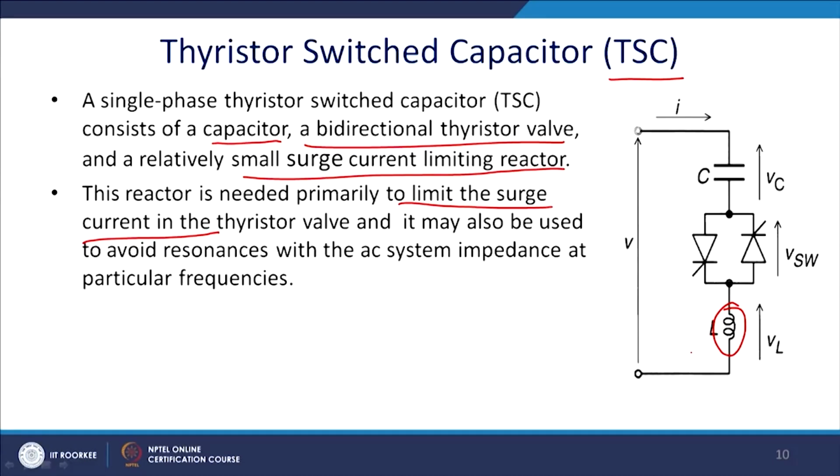So, ultimately this will be used for actively damping these devices, because the capacitor and the inductance in the power system may cause resonance, and thus we need to prevent that resonance. For this reason we have placed an inductor into the system.